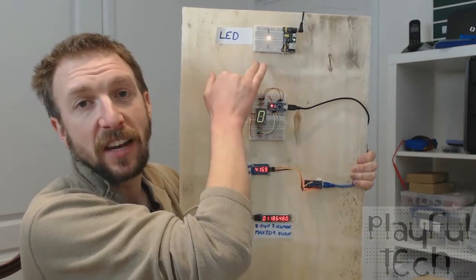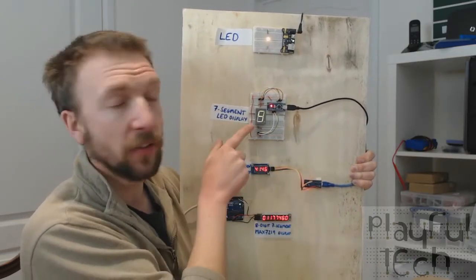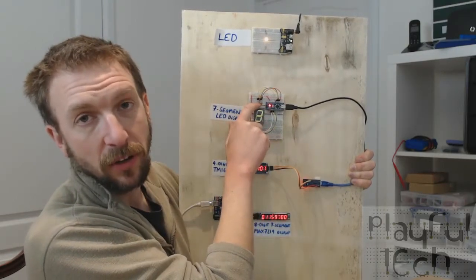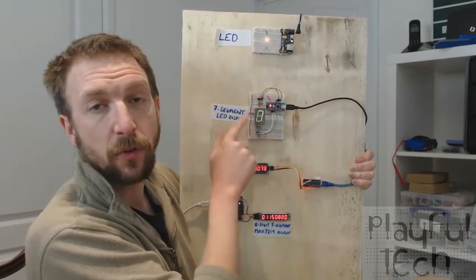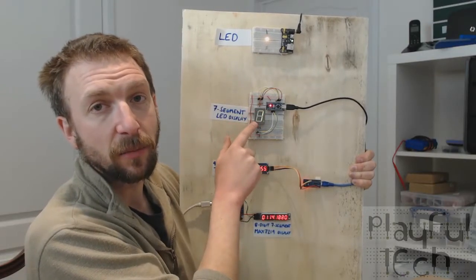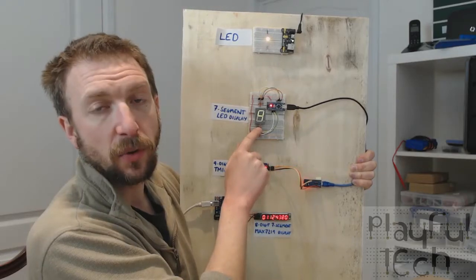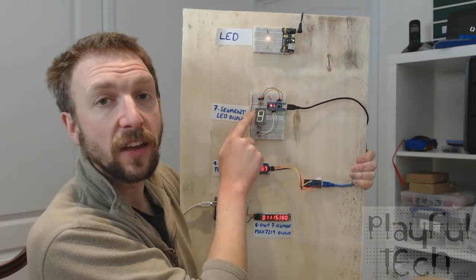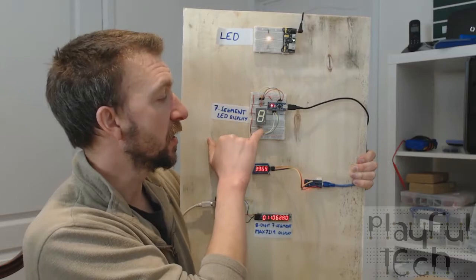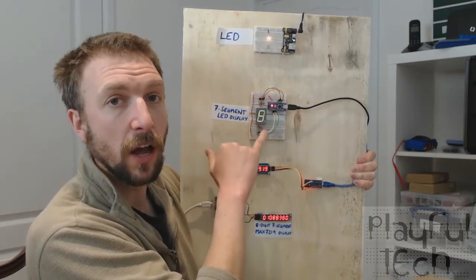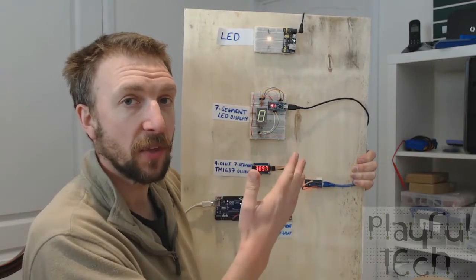If you remember what I said about the LED, if it's a common anode, which is what this one is here, I've got a 5-volt input at the top, which is shared between all of the different LED segments. Then for each of these individual wires, if I want to light that segment up, I set that to ground, or I do a digital write low effectively, which is the same thing.